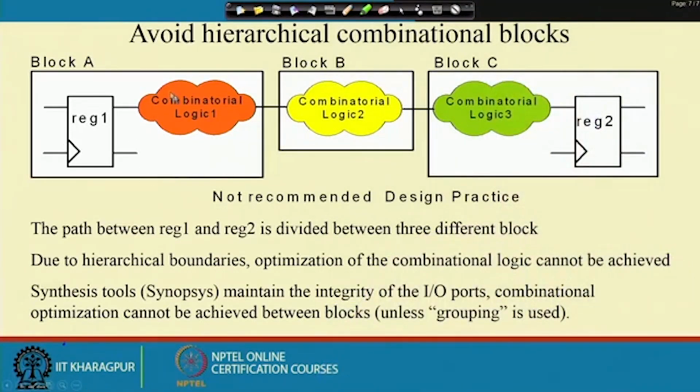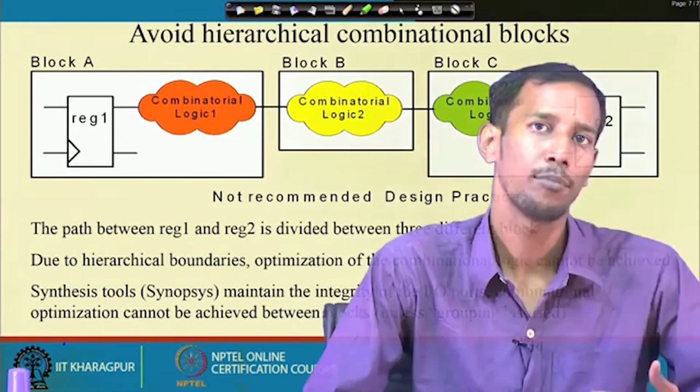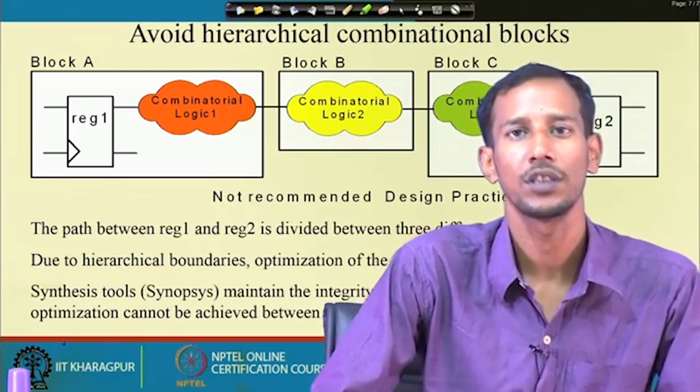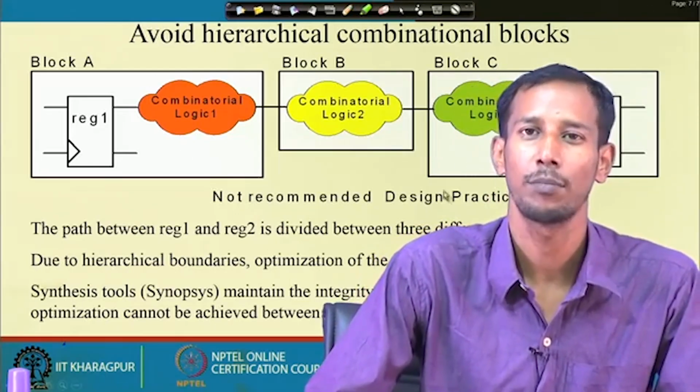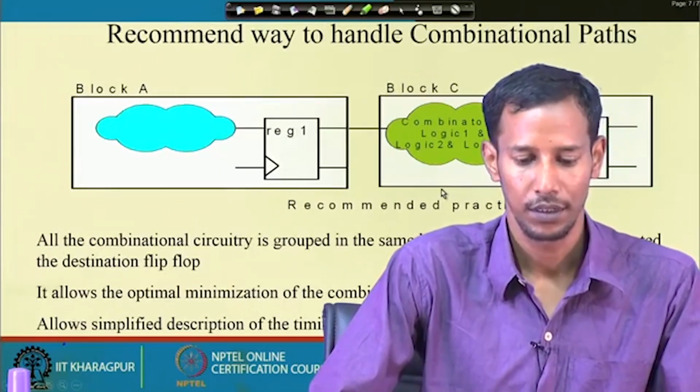So instead of putting different sub-blocks of combinational logic in between register-to-register connections, you club them into a common combinational logic, where the synthesis tool can easily apply the optimization procedure and give you a better result. As a designer, you have to avoid this type of hierarchical combinational logic.